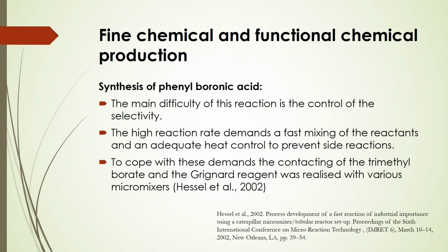Also, these microreactor systems are important for the application of fine chemicals and functional chemical production. In this case, if we consider the synthesis of phenyl boronic acid, the main difficulty of this reaction is the control of selectivity and the high reaction rate that sometimes demands fast mixing of the reactants and adequate heat control to prevent side reactions.